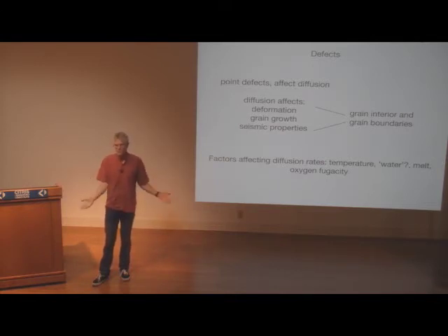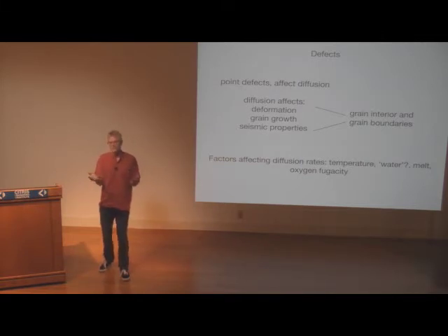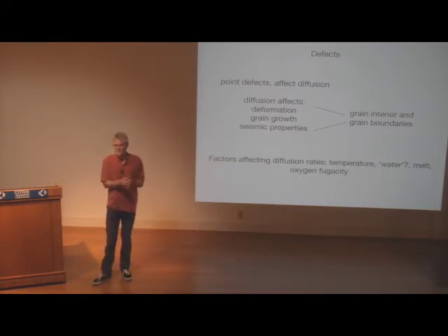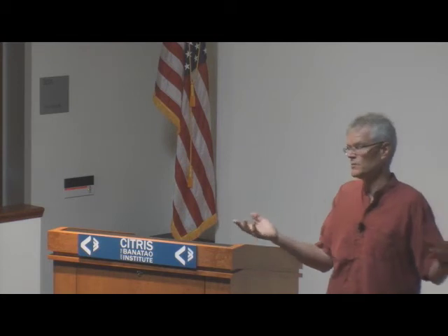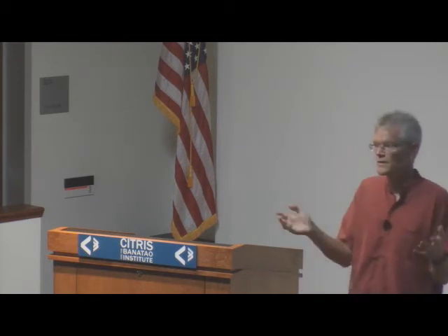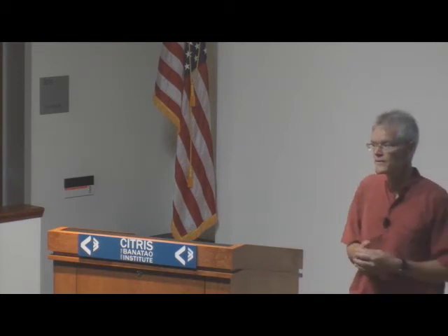So we just assume that hydrogen in that sense behaves like all the other trace elements. The more you have in the grain interior, the more you have in the grain boundaries. That's as good as it gets, but then apparently in the grain boundaries, it does not control the properties of the grain boundaries in the same way it does control the properties of dislocation motion. It's one trace element among many in the grain boundaries.